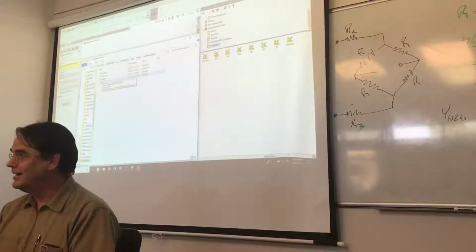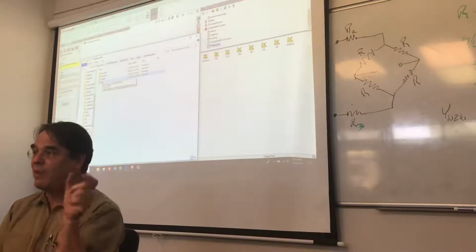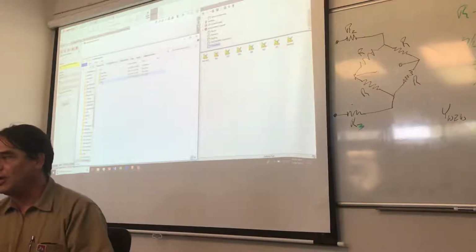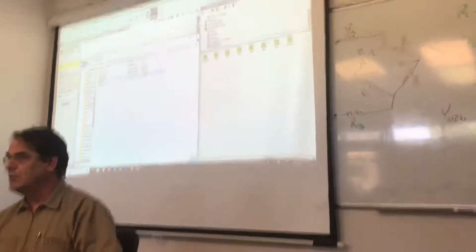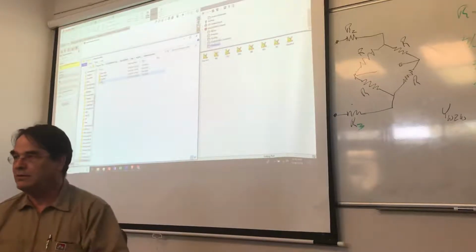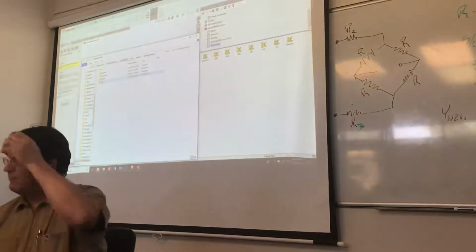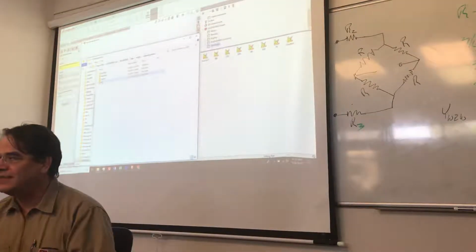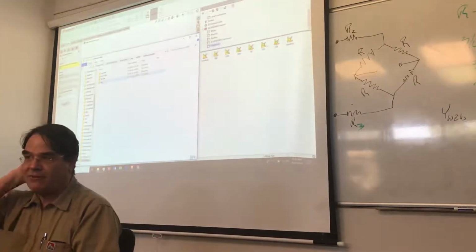You'll copy it in there anyway, because anything in the Program Files directory wants you to have administrator rights to change it. What they do is they build a hierarchy of sizes and types. There's a directory tree that starts under weldment profile, and this is where everything goes.